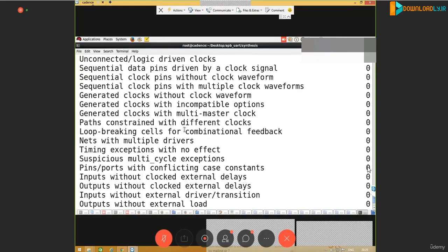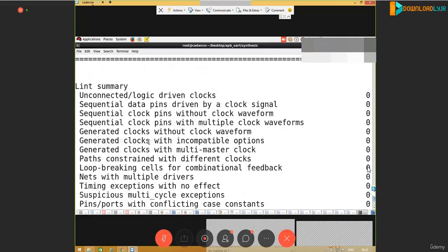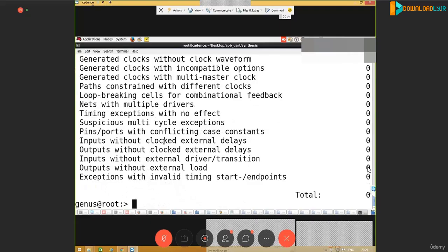For the RTL you have read and the SDC you have read, if the RTL has any unsynthesizable constructs, or if something in the SDC is not defined in your RTL, it will link both RTL and SDC and check for errors in both files. Once this is done, I will show the linting check report again. So report timing lint checks the syntax of your SDC file and any unsynthesizable constructs in your RTL file.